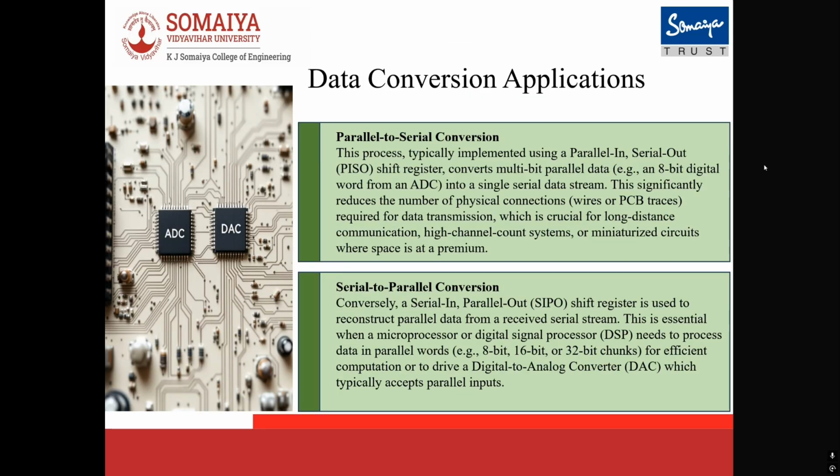Data conversion applications. Shift registers are extremely important in data conversion systems. First, in parallel to serial conversion, a parallel in serial out (PISO) register takes multiple parallel inputs like an 8-bit data word and converts them into a serial stream. This is crucial in reducing wiring complexity and enabling long distance communication.